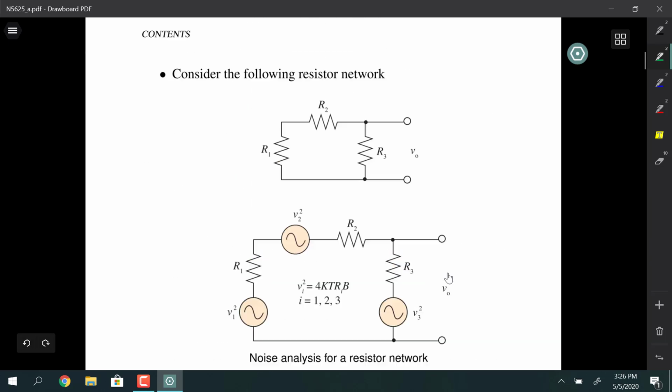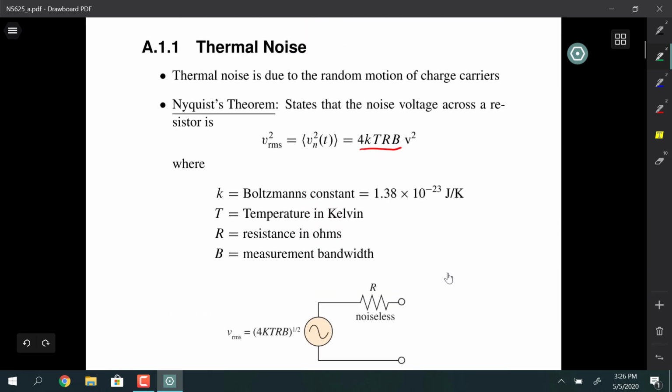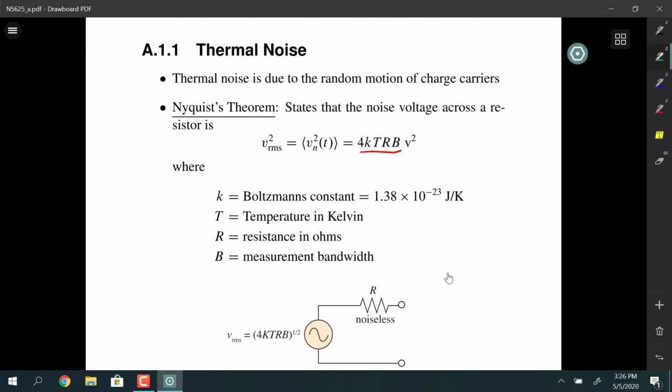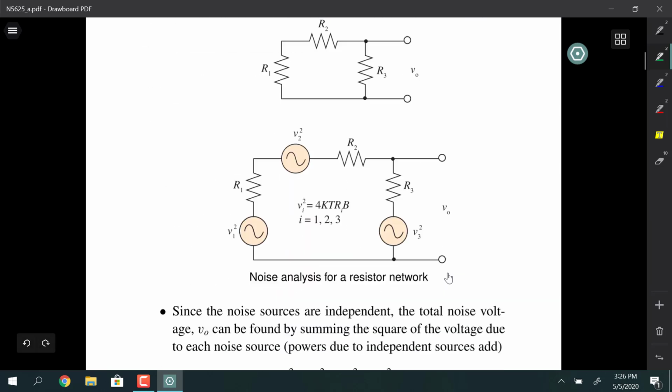We started with simple resistor circuit ideas, and it came down to this simple model, 4kTRB. So it's really kTB noise, or thermal noise, is what we'll be getting at, because we're going to be getting the impedance R to actually leave the equations when we're doing maximum power transfer. Don't see that just yet, but we'll get it down to that point.